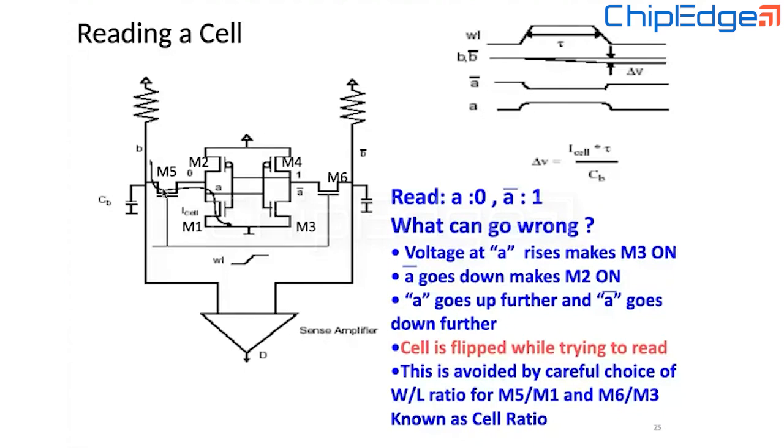As we see, when the bit line is discharging, it is discharging through M5 and M1, right? And for M1, we said that the gate of this NMOS is 1, and this is 0, and this is also 0. So VDS here is 0, and the gate is 1. So VGS is there, but VDS was 0. So why was this discharging then?